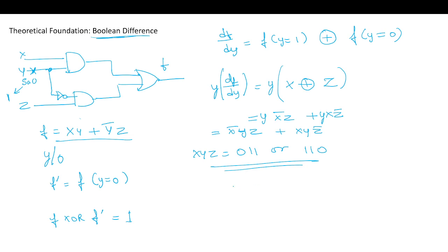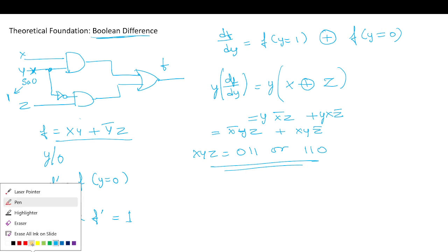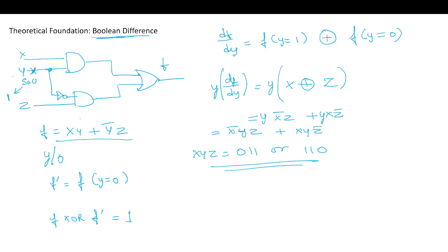Now if you substitute these values, you can verify it from our previous method. We set this to be 1 and we want to propagate this here, so the value should be 0 and 3 is 1. To get this here, we wanted a non-controlling value here and this became 0. So this output is 0 anyway.